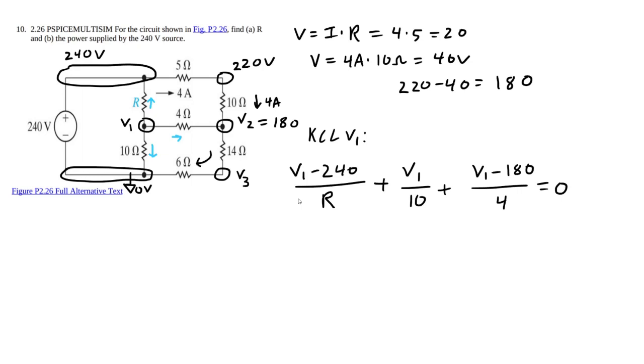If we have these two resistors in series, 4 plus 16 ohms is 20 ohms. So the voltage drop across that is known because these two are in series. So the voltage drop across them in total, we don't have to worry about V3 anymore, because V3 won't give us any information except for the current through this resistor, but we know that, so why would we bother?